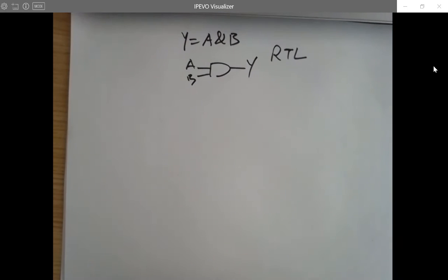So, if you make the transistor bigger for the flash, probably it is able to handle the 20 volts. So when you are running the bare-bone microcontroller on the breadboard, you don't need anything else, right? Which means the flash is right in the chip. You just grab the chip and plug into the breadboard. You don't have another flash chip externally, and can directly burn the program into the microcontroller, and it runs. It memorizes all the programs, right? When you power it off, it's not losing any information. You can still run it next time you power it up. So the flash is directly inside the chip.